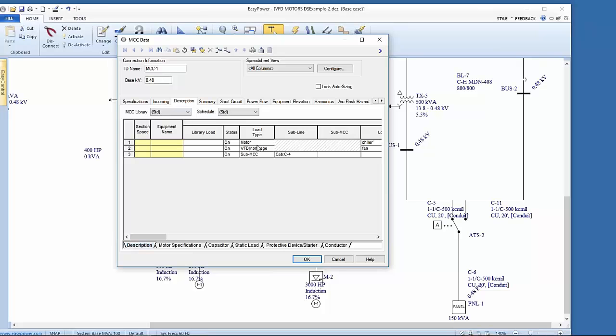As we go into the motor itself, under the description of the load, the choices that were permitted range from a standard motor to a standard load, VFDs, subpanels, motors with TCCs, VFDs with TCCs, and so when this is a VFD motor, we can choose non-regeneration or VFD with a TCC, and at that point, as we tab across, we'll be entering the same data that we would on a motor, and then the parameters as far as what's required to do the calculations for short circuit and arc flash are basically very similar to what we set up as a standalone motor.